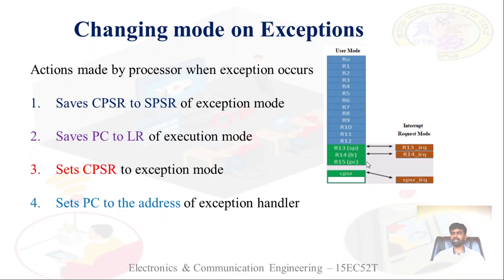That means five exception handling processor modes are present: IRQ mode, abort mode, undefined mode, SVC mode and FIQ mode. Each has its own SPSR, the saved program status register, indicated for example by SPSR_IRQ for IRQ mode.